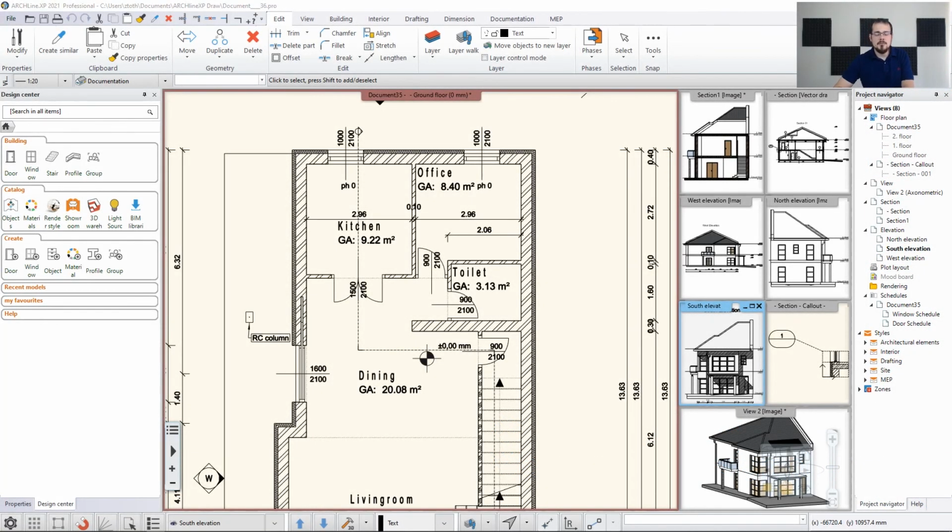It might happen that your building project consists of elements which should be demolished, and you want to show multiple instances of the same floor plan with things which would be demolished and built later on. Of course, you can go around and select elements and delete them, but that would be a destructive way of modeling and you would have no original plan to refer back to. Luckily, in our software there's a tool for this kind of change tracking, and that is called phases.